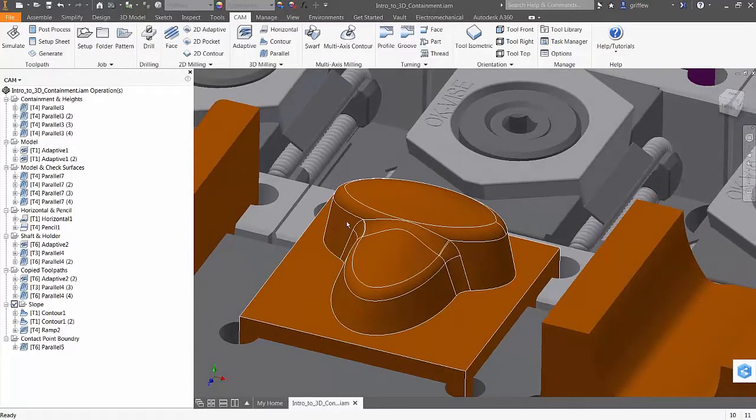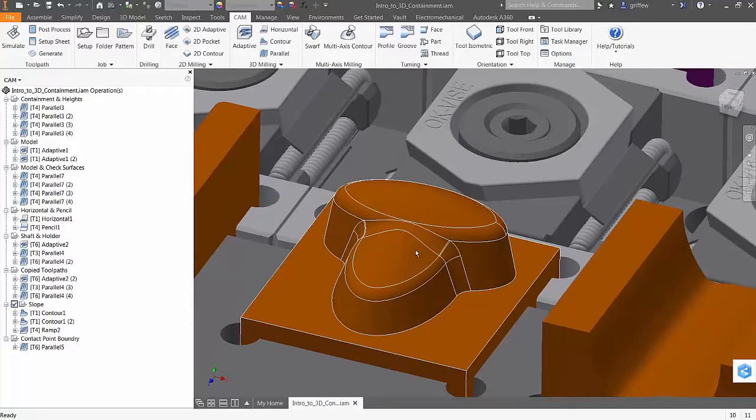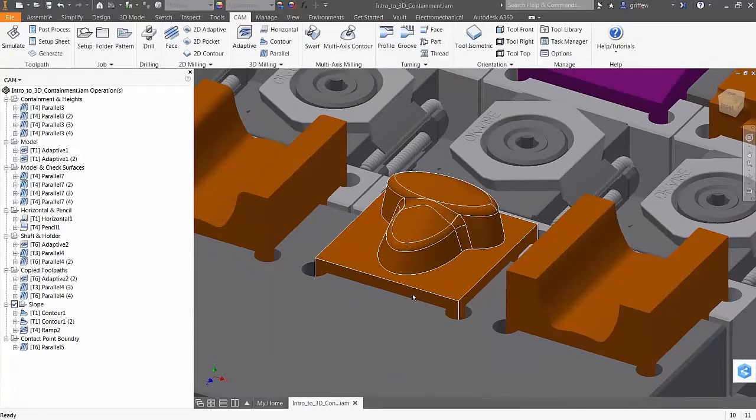So as you walk down, you think you would have less code, but it all depends on the number of points, because now as it steps down, if you're doing linear, depends on how your tolerance is set up, you would get a lot more code because it's constantly moving. You're constantly getting points in the X, Y, and Z.